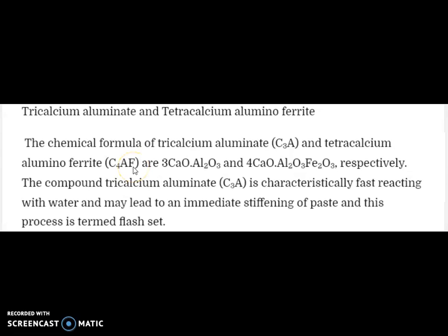Now, tricalcium aluminate will be written as C3A and tetracalcium aluminoferrite will be written as C4AF. You have to get used to these acronyms or the ways to depict these compounds, okay, because their chemical equations are a little complicated. The compound C3A is characteristically fast reacting with water and may lead to immediate stiffening of the paste. Okay, this process is called flash set.